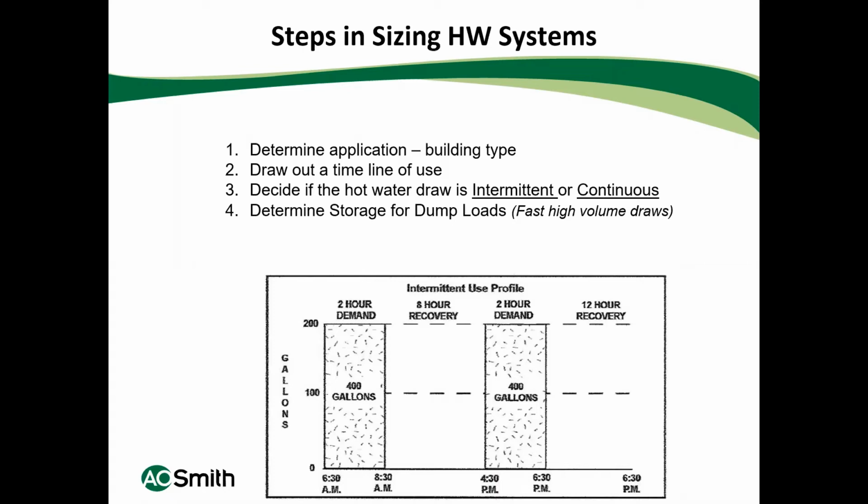And those are fast, high volume draws that generally most water heaters can't provide on a minute by minute basis. So you want to have all that water in storage. We'll talk a little bit more about that in a second. And then of course, you're going to calculate both your storage and recovery rate. And the nice thing about ProSize is it does that for you.